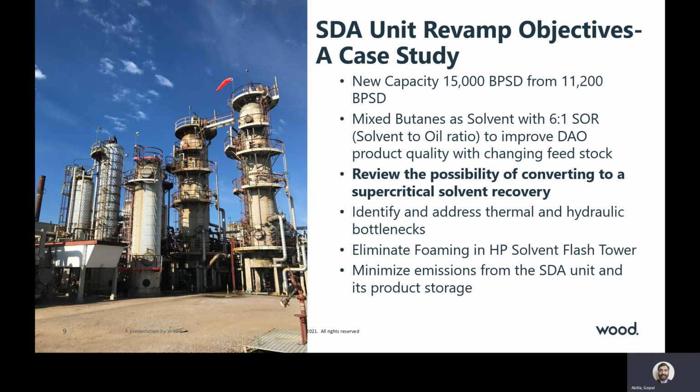Review the possibility of converting to a supercritical solvent recovery. Identify and address thermal and hydraulic bottlenecks. Eliminate foaming in HP solvent flash tower. Minimize emissions from the SDA unit and its product storage. So these were the main objectives, which is essentially typical in most of the units.